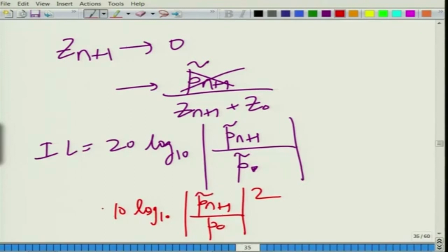Basically, for a constant pressure source, that is if the source impedance is 0, if we just measure the acoustic pressure without the muffler on and with the muffler on at a given location, so P n plus 1 and P naught, and let's take this ratio. Actually, this will be n, I am so sorry. Then we are going to get the insertion loss, and this will be shown to be equal to the level difference in the limiting case.